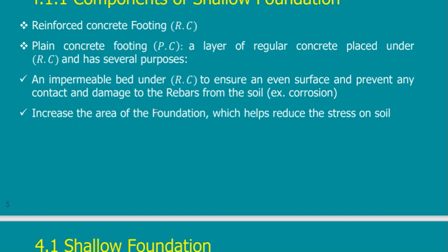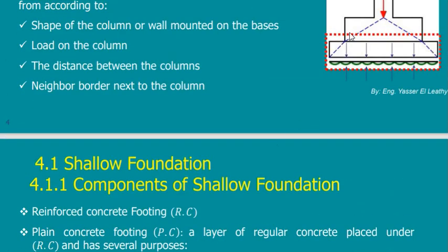The other thing is, if I put adequate thickness, then I can depend on it to be part of the foundation. I can use it as part of the foundation, and in this case, you see this drawing, this is the RC, and this is the PC. If this PC is very thin, then this one will have to increase, will be bigger, because it will take all of the load, and the other is just a membrane, as if you are putting a membrane on the soil.